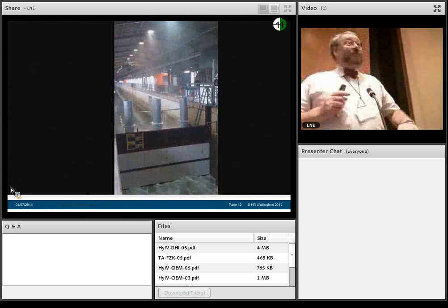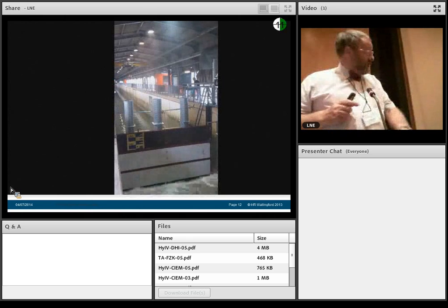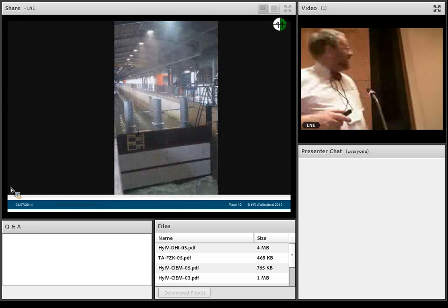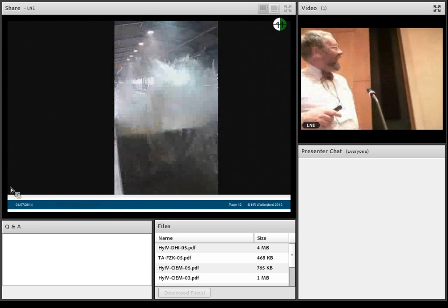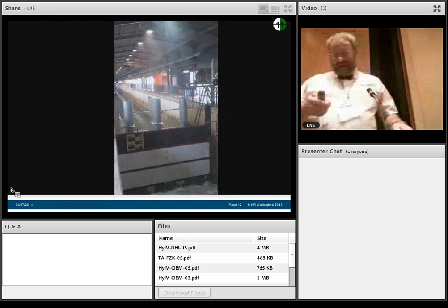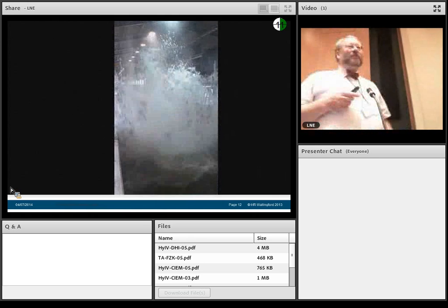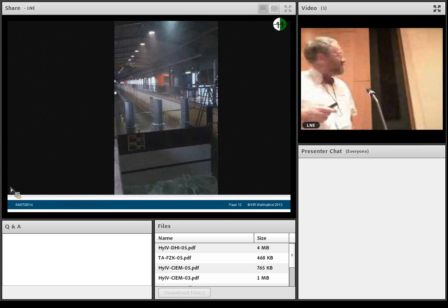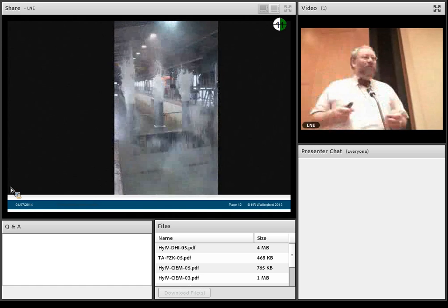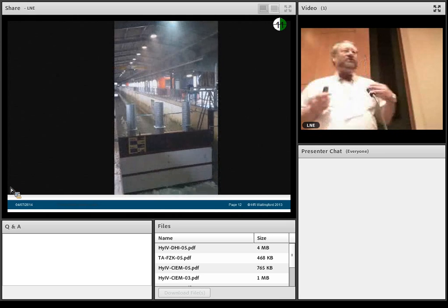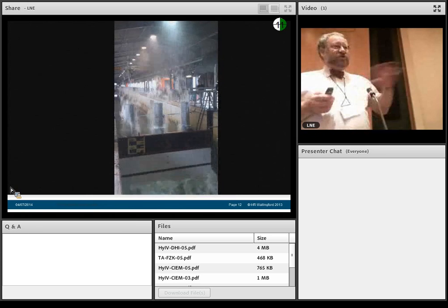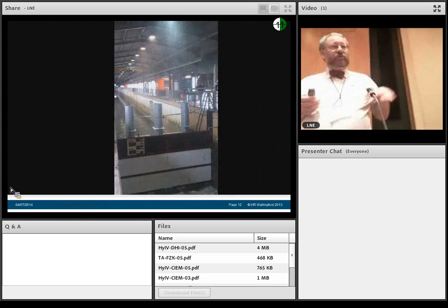So by the time the solitary wave got to the caisson, it was over a meter, and there was a loud bang as it hit the roof of the... So this is our test. As John Alderson said, I think Matthias had been stung by a wasp. So this was not directly intended, but almost certainly this is the situation that caused major structural damage to the roof of the Mutriku device.